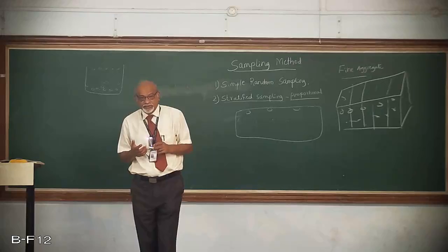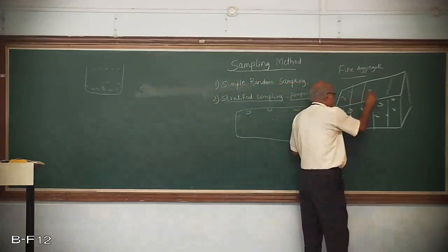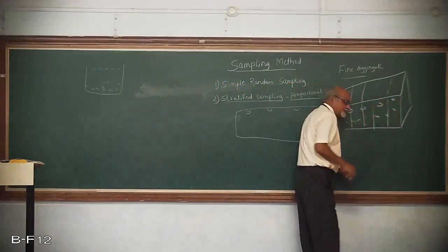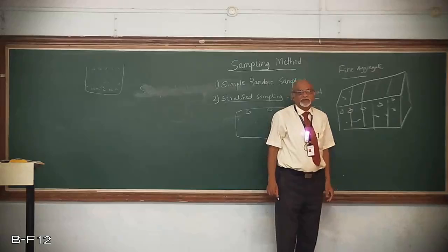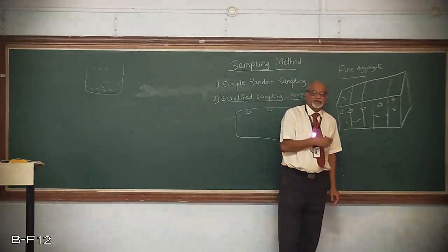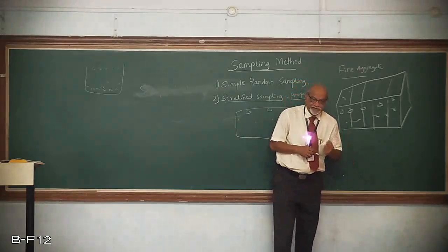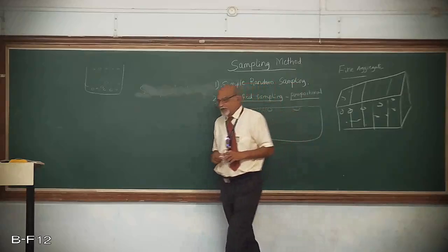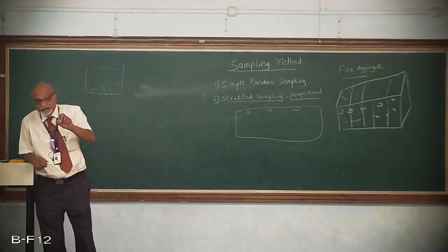Is it understood? Okay? That means, say, for example, I have divided into some 6 sublots. Again, from each sublot, in proportion, I will divide it into 1/6 of that one, whatever it is. And then I will collect the samples. These number of subsamples collected should not be less than at least 2.